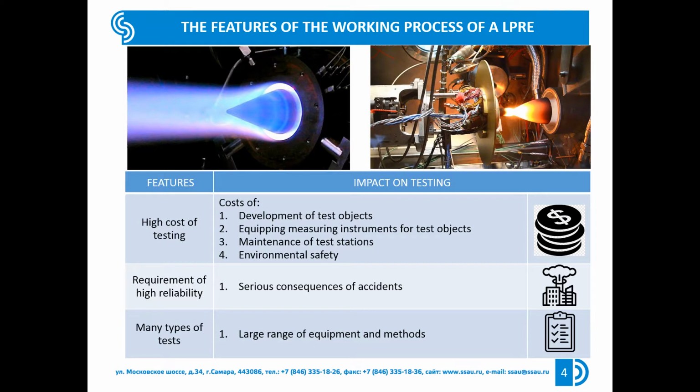External factors include pressure and temperature of fuel components at the pump inlet or engine inlet, turning angles of thrust regulator actuators and component ratios, and internal factors include variation in size of constructions and hydraulic characteristics of throttles, lines, and gas paths. This, in turn, makes it necessary to simulate all possible conditions during tests, which of course increases their time and cost, and also expands the range of equipment required.